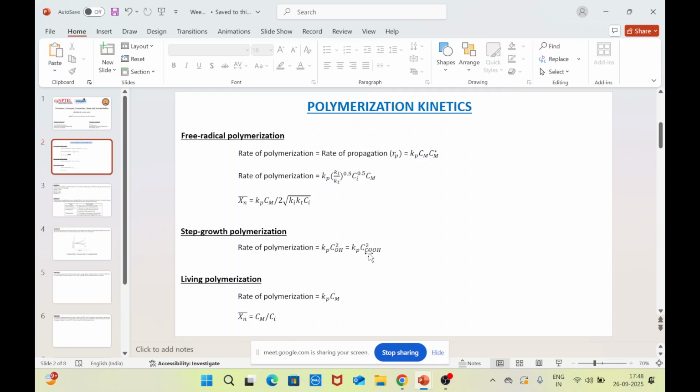In case of the Newtonian fluid, they obey Newton's law of viscosity, which is nothing but shear stress is directly proportional to the strain rate, with the viscosity as the proportionality constant, as many of you might know. However, in case of non-Newtonian fluid, this relationship does not remain valid anymore. Here, the shear stress is not going to be proportional to the strain rate.